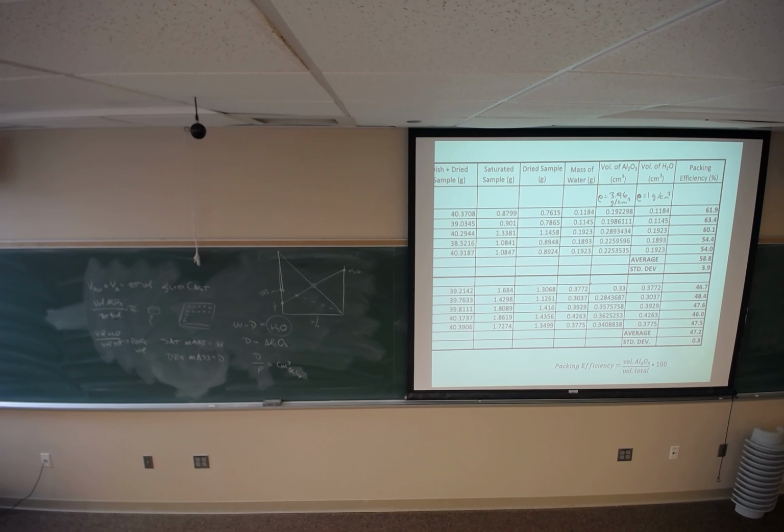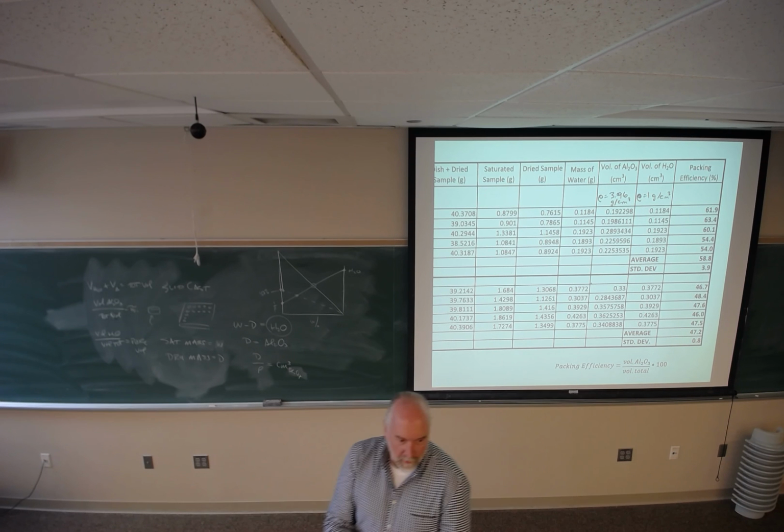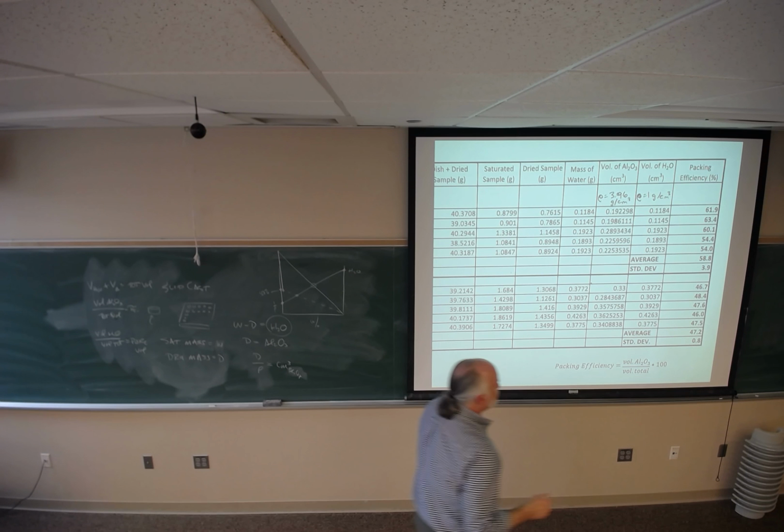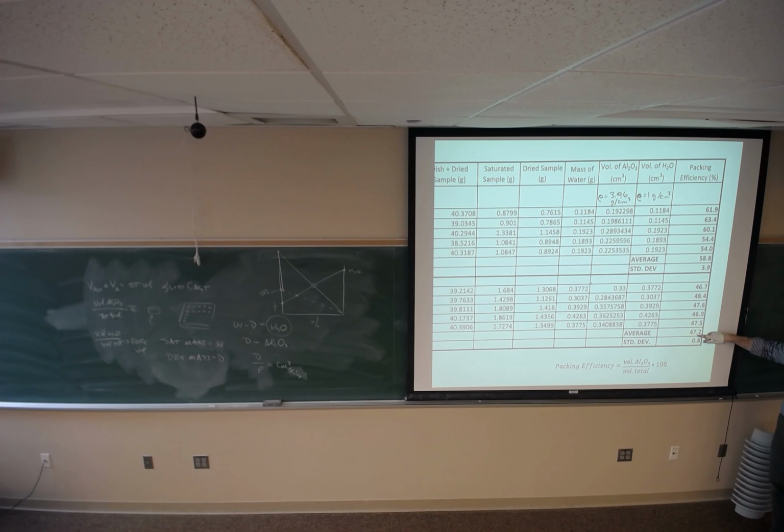Because for the dispersed, they were taking so long to cast that I had slop. There are a couple of ways around that. You could cast, decide to stop, screed off the top of the pellet that's still suspension, and measure what's left. You pour this in here and the material is going to cast. It takes time, but you just pull the pellet out, scrape off the excess liquid, and weigh that. That speeds it up. And here, for the flocculated, he gets 47% plus or minus 0.8.